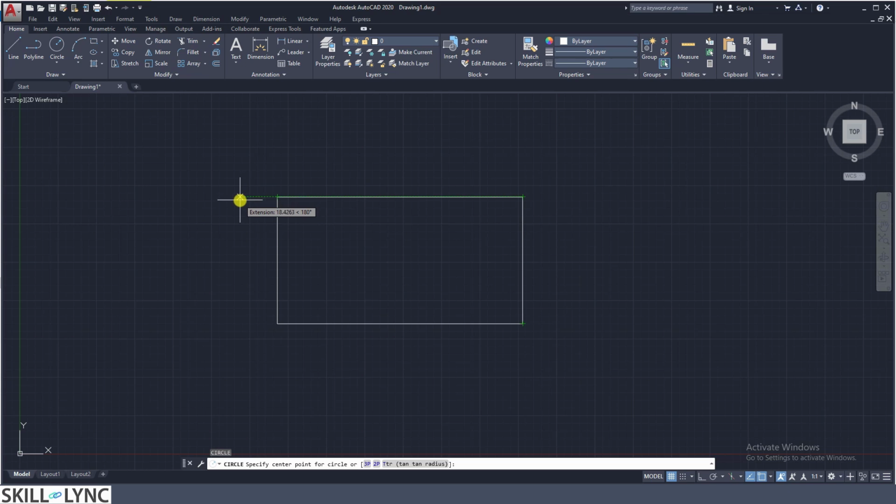If you could recollect the relative polar coordinate system that we were talking about in the previous week, you can see it is showing a relative position 18.6696 from the point at a polar angle of 180 degrees, and if you go this way it's 90, and so on. So now it's again snapping to exact rectangular polar, that is, it is snapping in the 90 degree, 180 degree perspective. But we also wanted the center point, so let's look into how it can be actuated. So let us go into the DSETTINGS.